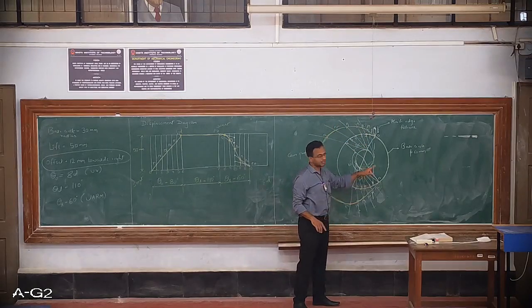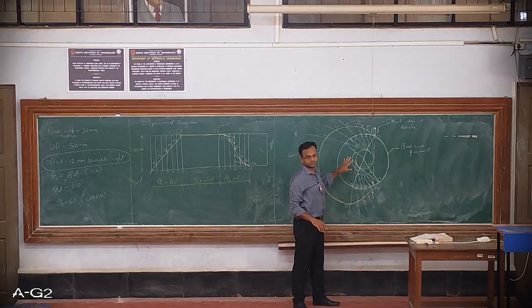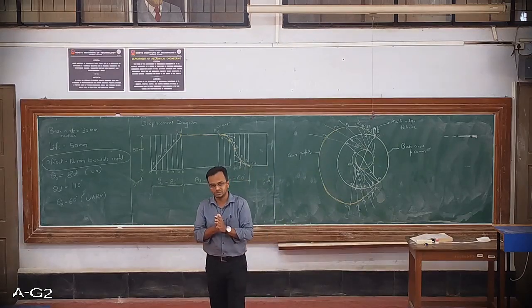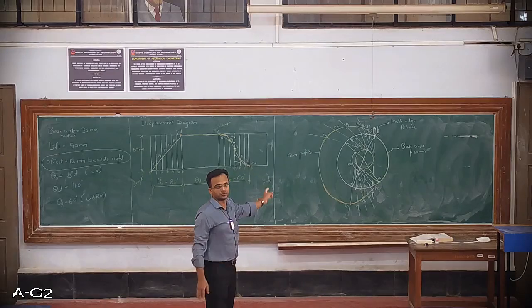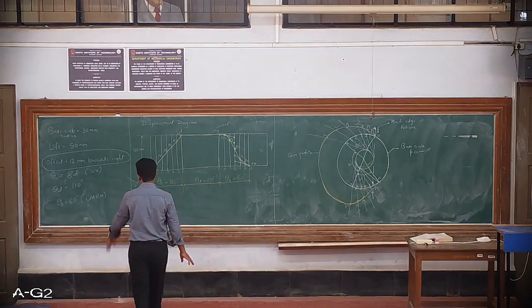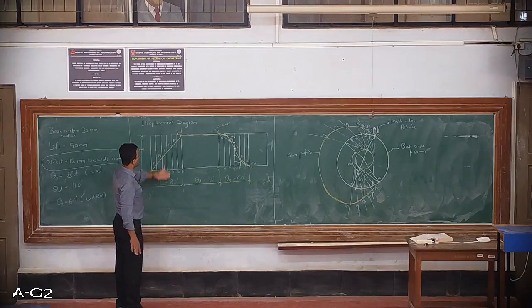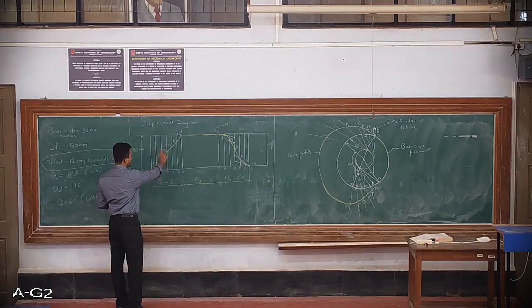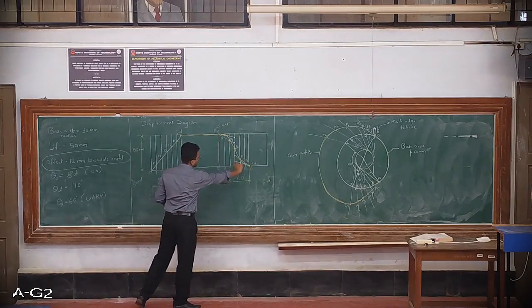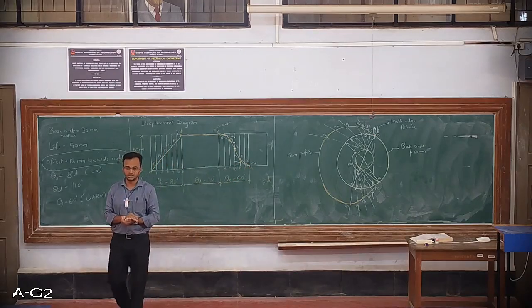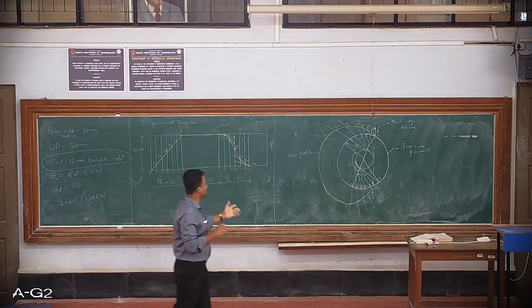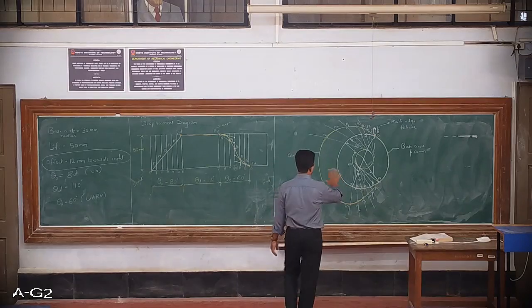To obtain the final CAM profile, whatever additional lines you need to draw or construct, ensure that you draw them with very thin lines and darken only the final CAM profile. The same thing will apply here also. So all these division lines we have made are only for our reference or construction purpose. Only the final orange color line I have drawn over here should be dark and clearly visible. Here, if I draw them very lightly, it won't be visible to you. That's why I have drawn all the lines a little bit dark.